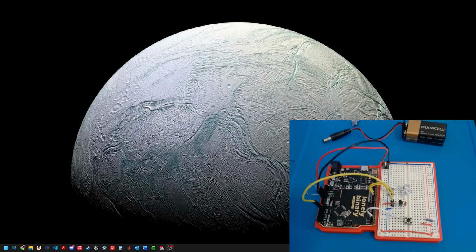As far as hardware, we're running on an Arduino Uno, and we have our temperature sensor connected to our analog pin A0. We are powering it with 3.3 volts, and it was important to me that I didn't want to lug my computer over to the refrigerator and have the USB connected the whole time, so I wanted to be able to run off of battery power.